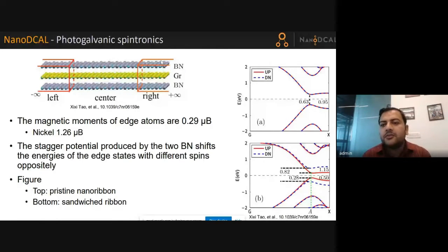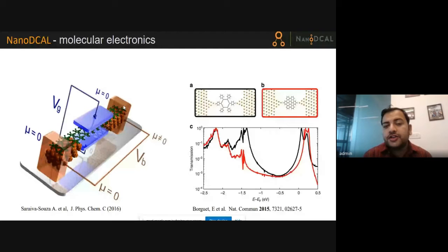If you want to define some electrode, that is also possible. So you can see the material is simulated and the band gap is calculated: indirect band gap, direct band gap, with spin up, spin down, magnetic moments, armchair, zigzag, and chiral vectors of particular parameters. The lattice of this particular unit cell crystal you can define, and find the electronic properties, and device properties will also become possible.